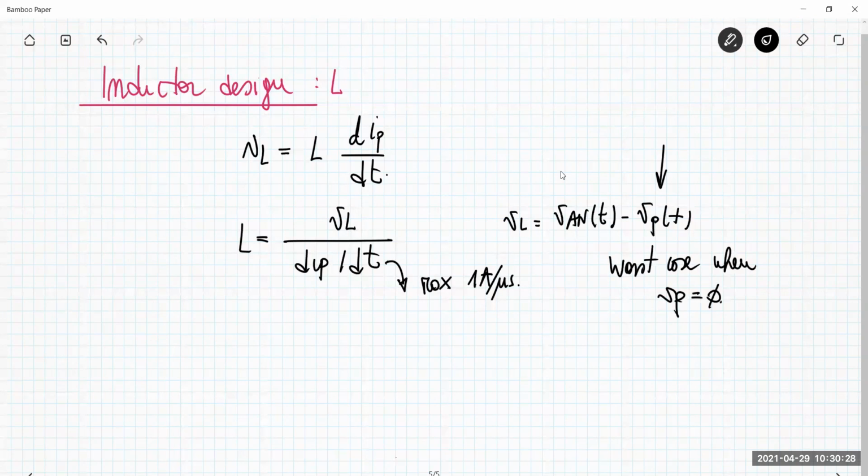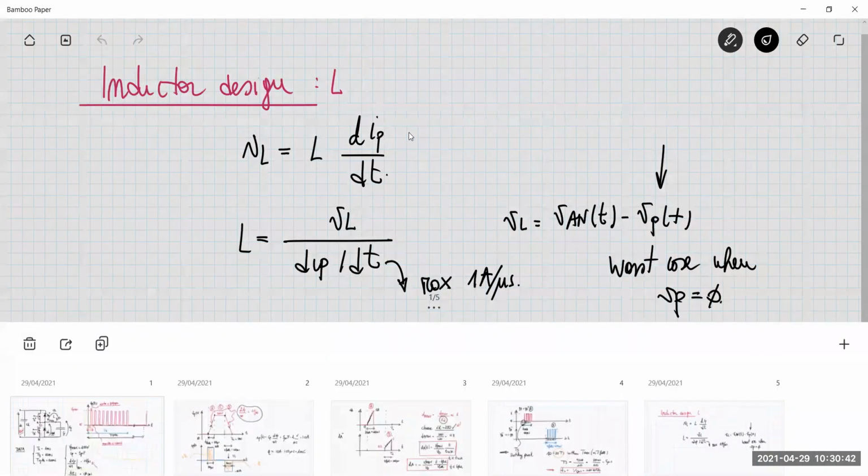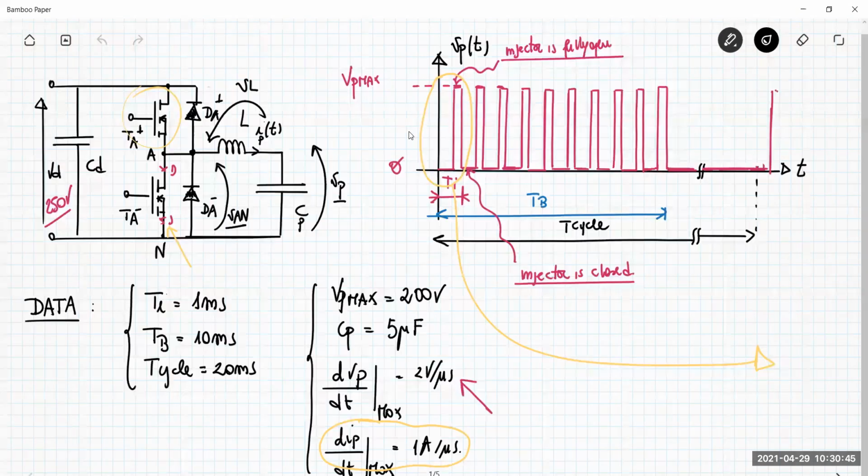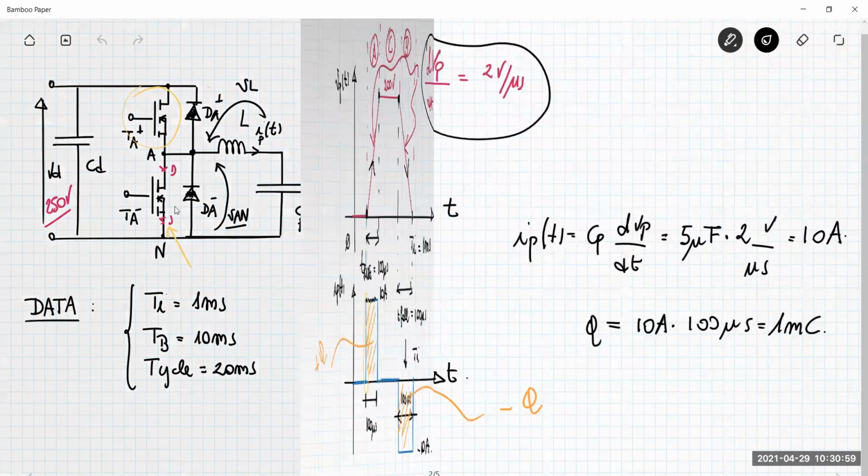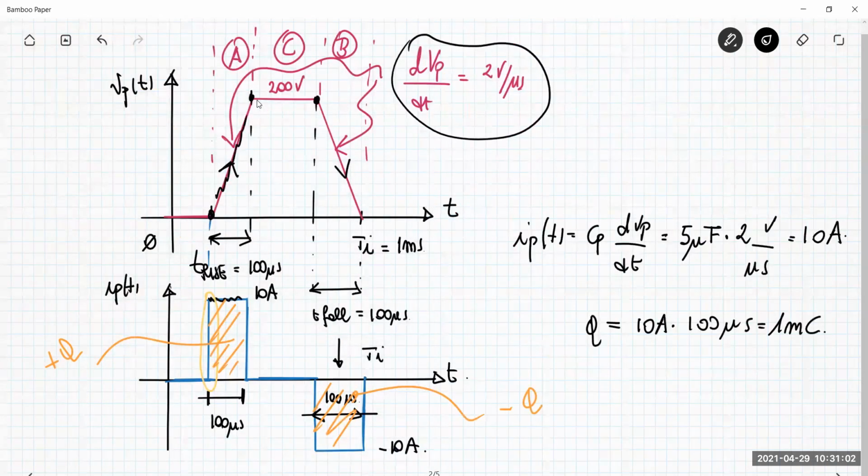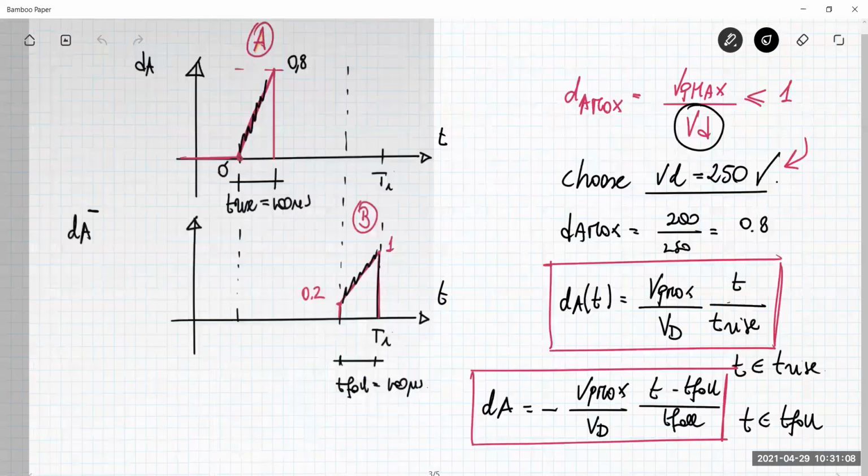And this happens at the beginning of each TI cycle, when the switching cycle starts, here the voltage VP is null. Then the charge that I'm providing by the half bridge makes it possible for the voltage across the capacitor to rise up, exactly in this way. But at the beginning of this cycle, the voltage is null. So this is the worst case for the inductance.